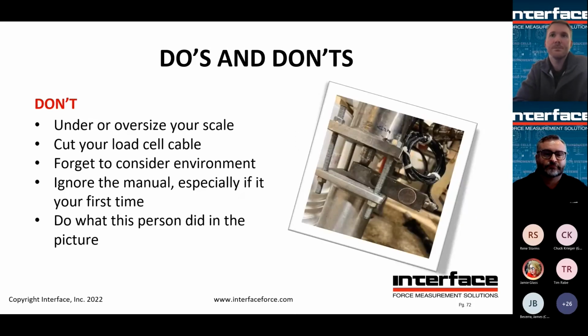Don't oversize or undersize your scale. I always give the example, give as much capacity as you can while achieving the resolution that you need. Don't cut your load cell cable. We've seen it, probably too often, where the cable is cut right at the cell, and there's truly nothing that you can do with that other than throw it away and get a new one.